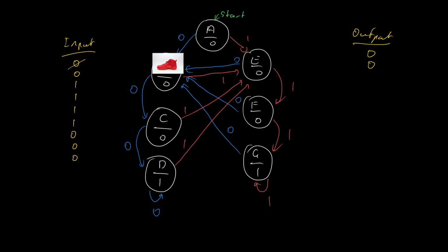So at the next rising edge of the clock, I can cross this off and I move my marker to this state here. And I observe that my new output is going to be a 0. So I simply mark down 0 here. And repeat again. In this state, the next input is a 1, so I cross it off, and I need to remember to move my marker.